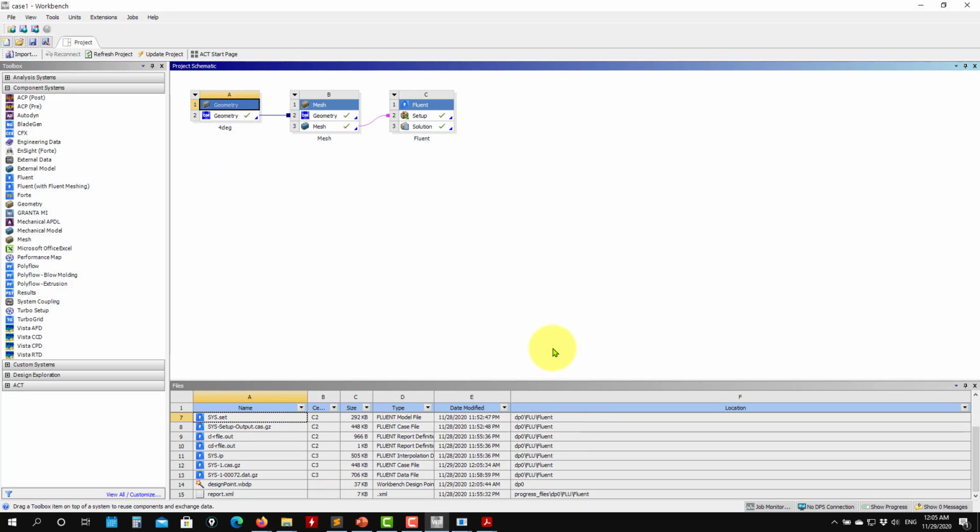As I said, I will ask you to run at least 3 angles of attack. Try to do, for instance, 0, 6 degrees, and 10 degrees. Do not go to the stall. Predicting a stall is also very difficult, but if you are curious, go and try to do a stall. But usually stay at 0, 4, and 10. That will be okay. And compare with airfoil results. So this is 4 degrees.